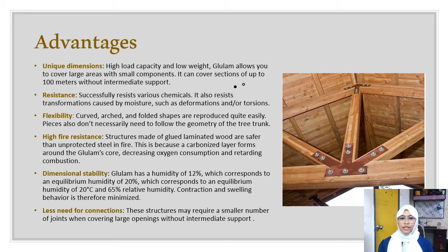High fire resistance: structures made of glue laminated timber are safer than unprotected steel in fire. This is because a carbonized layer forms around the glulam's core, decreasing oxygen penetration and retarding combustion.